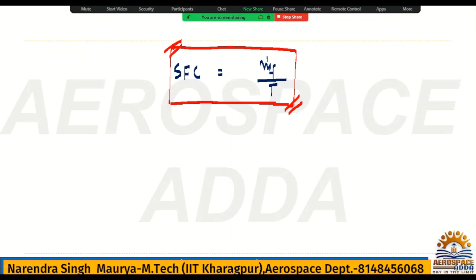So this is related to SFC. Now, for SFC you also need to concentrate, they can ask questions based on this point. SFC increases when you are burning more fuel, SFC is also reciprocal to thrust. So in any engine where the mass flow rate of fuel required is more, like a ramjet engine, you will burn more and more fuel, so SFC will be high.